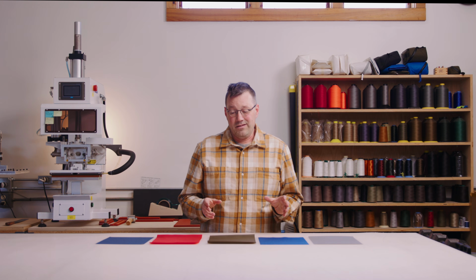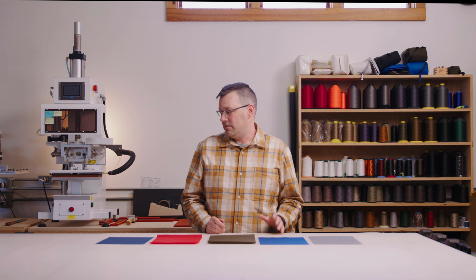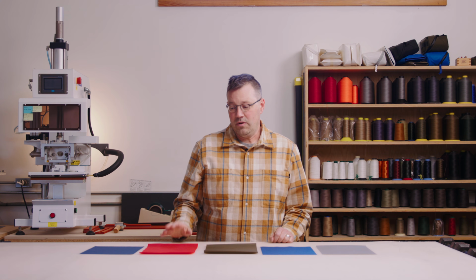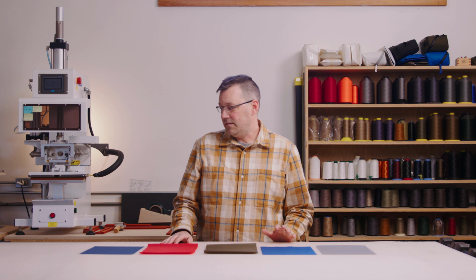All of our main body textiles are plain weaves, or 1-by-1 weaves. What that means is that every yarn, as it passes by a pair of perpendicular yarns, goes between them. And so every yarn intersects with every other yarn, 1-by-1-by-1-by-1-by-1. This is the simplest and most common type of weaving. It is the only type of weaving that we use in our linings and main body textiles, and it produces a surface that is smooth and regular and even. And because all the yarns are interlocked together, it also produces a material that's very strong.